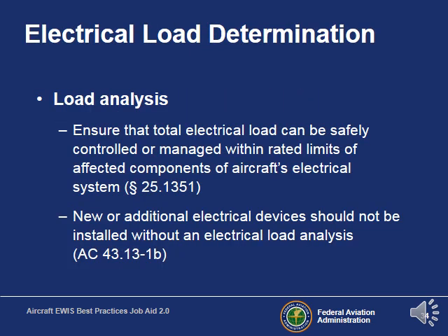If any equipment is added to the aircraft, there needs to be a load analysis. Now, typically, when we add aircraft components to our aircraft, they come with an STC that has already done the load analysis for us.